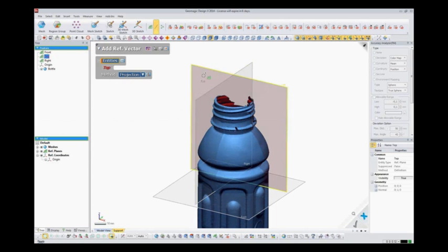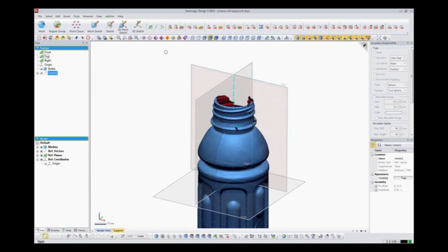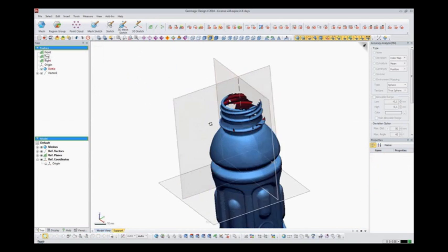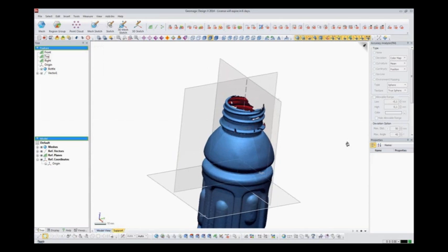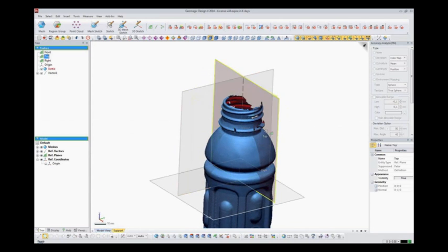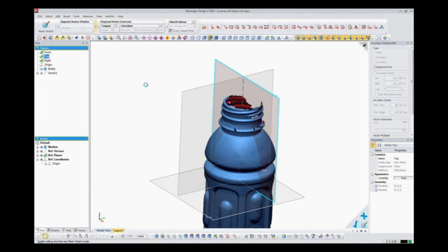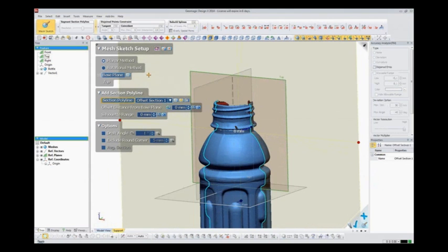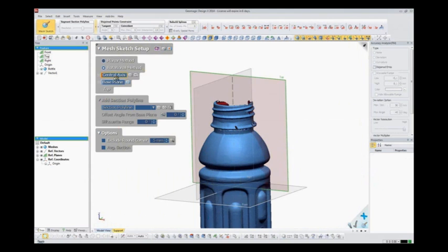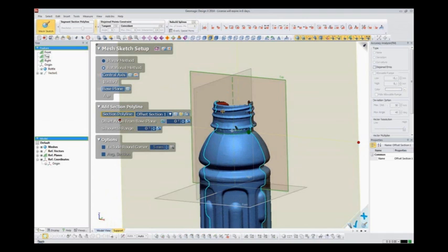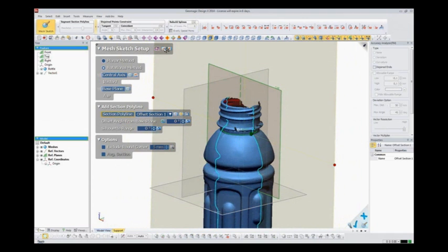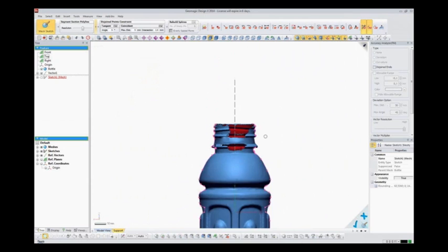So I will generate my axis between those two planes here, and I will choose one plane from which I start with my revolving sketch on this side. So I can do that base for the helix first. So this is my revolving sketch.